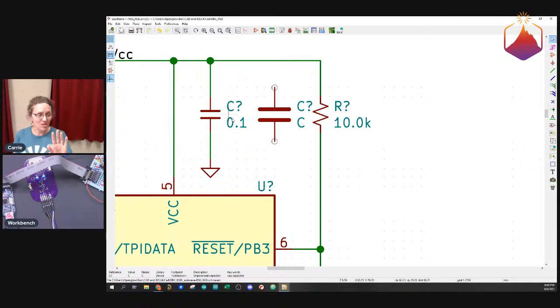The other legitimate reason for making this smaller is that a lot of times you might have a row of capacitors together, because you need capacitors of different values. Let's say you have a power converter and it needs 22 microfarads of capacitance hanging off the end of it to smooth out the noise and have a nice stable output.